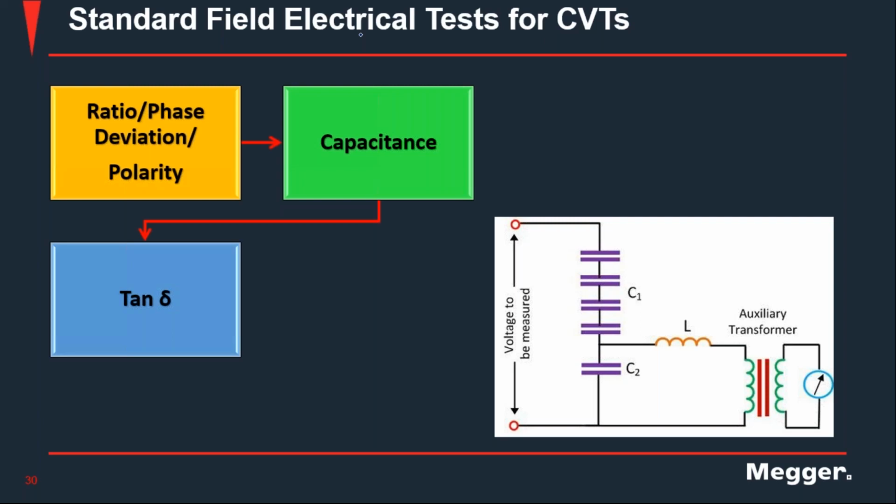This has to do more with the application of that particular instrument transformer. Where do you have it installed? What is the purpose of that instrument transformer? Again, there is no exact number or limit in terms of number or percentage that you're looking at. Once you get your knee point from your measurements, you want to make sure you are operating within the linear performance of that CT. If you can help me show a saturation curve.